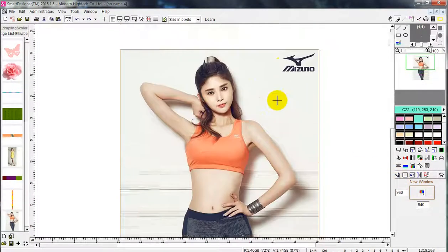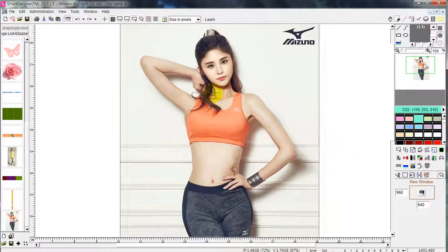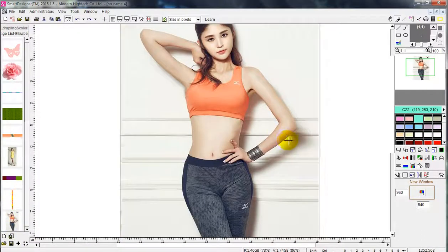Now if you don't select this as a whole image, what's going to happen is that since this portion of the model is selected using the irregular image window, when you click add to image list, only this tank top will be added to the image list, and that doesn't really look good because you want to see it on the model rather than just see part of it.